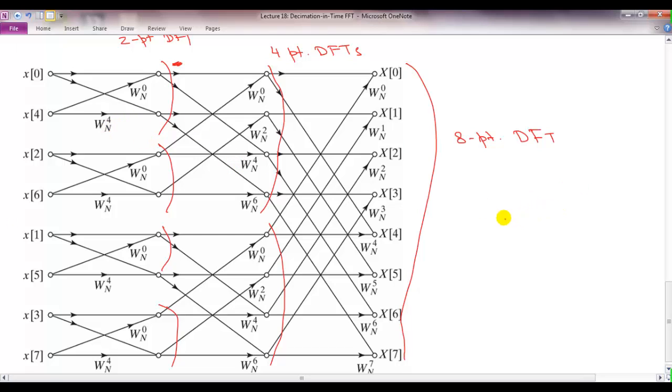You can try to remember this butterfly diagram by thinking of, like, now you can start counting your stages. For example, previously we were starting from the end point and going backward. We had a length 8 sequence, we went to length 4, 2 sequences, then we went to length 2 sequences, a total of 4. If you want to go from this end to the end point, then every computation is simply given by this butterfly diagram.